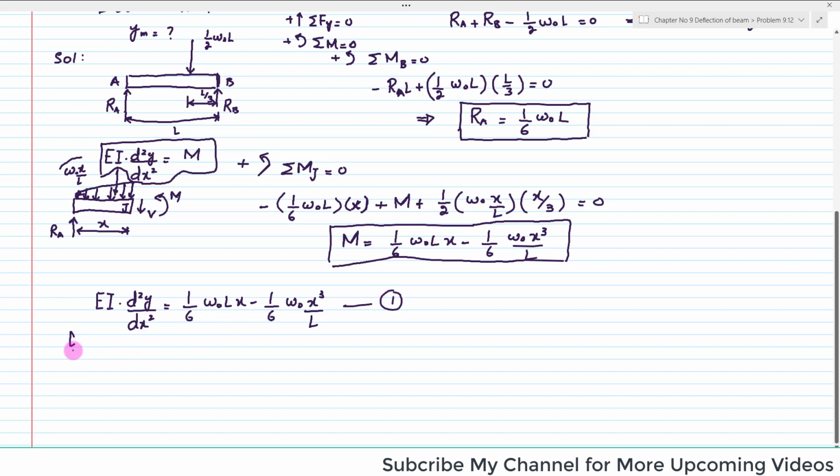So integrating equation 1, we will get EI into dy by dx is equal to 1 over 12 W naught L x square, and it will be minus 1 over 24 W naught x4 over L plus C1.